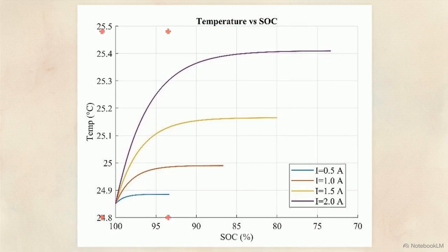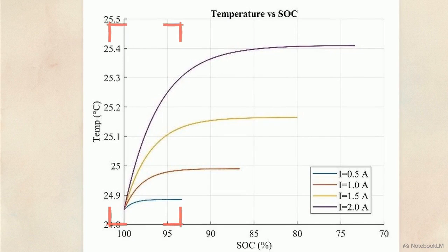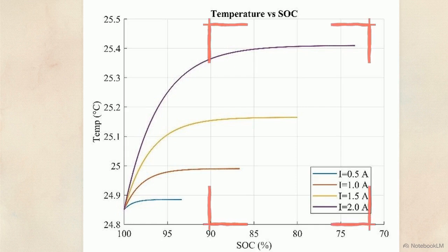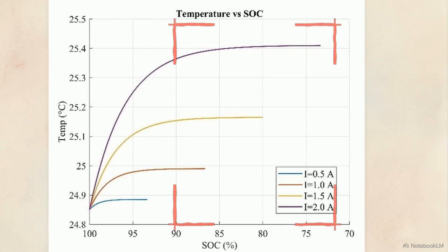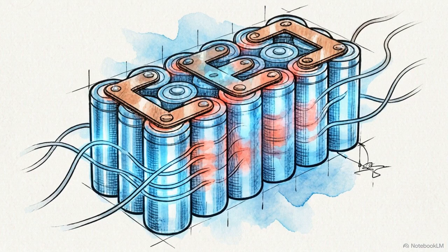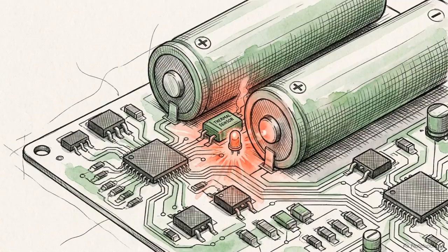The curves show a sharp initial rise early in discharge, confirming resistive heating is prominent before internal temperatures stabilize. Eventually, the curves flatten as heating tapers off, and the pack approaches thermal equilibrium. Although this 4S3P pack remains thermally comfortable under these modest currents, the 19-fold escalation in heat indicates how quickly stress compounds. This nonlinear relationship establishes the need for load-aware thermal safeguarding within BMS protection logic.